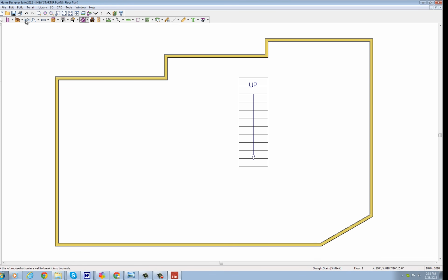And then you'll just take your wall tool. I'm just messing around with it right now, but say half of your basement was going to be a storage room, and then this is all storage over here. Then you just do that. Go over here to your door tool and pop a door in there, and boom. Guess what you have now? You've got a storage room with a set of steps coming down into the basement.